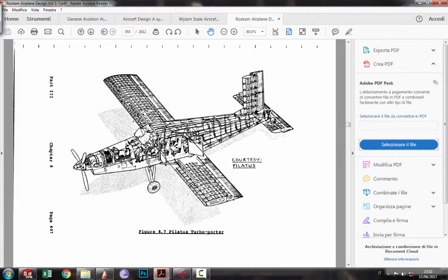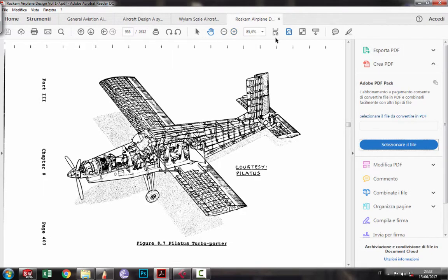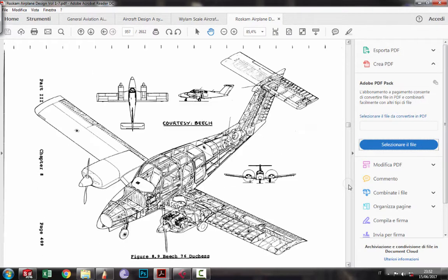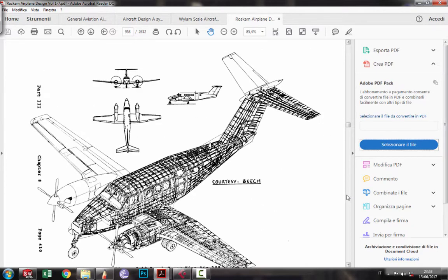This is the vertical rudder, it is outside the wake. We can see also here that the vertical wing is a little bit aft of the horizontal stabilizer. So this is for spin recovery. In this case, we do not have the problem, because the T-tail is better, because we have the wake region during stall. The vertical wing is outside the wake, so it is another advantage.